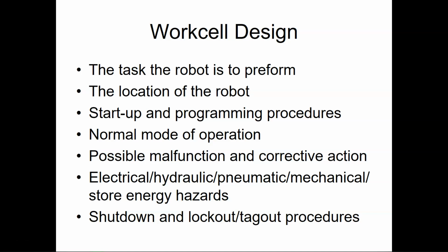So if it's hydraulic powered, maybe I have a hose crimped somewhere. So I need to make sure that everything that's part of that system is drained back to the tank before I begin working. And I need to make sure everything is shut off to where I'm working at so that nothing gets switched on either by accident or, God forbid, on purpose.